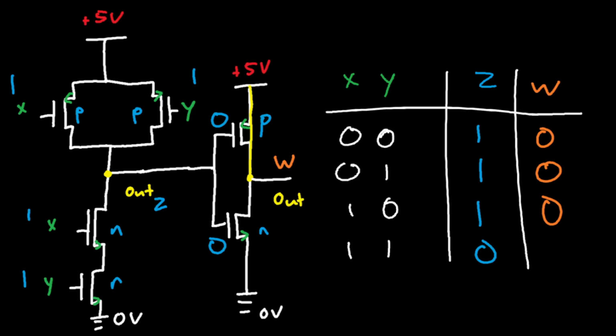So we have the current going down here, hitting this node, but the current can't go past this transistor, so it doesn't reach ground. Good thing. Now this current goes all the way down, hits this node, and this voltage reaches this node as well. Since the voltage reached the node, we have a voltage of between 3 to 5 volts for the output. And 3 to 5 volts for the output stands for an output of logic 1.